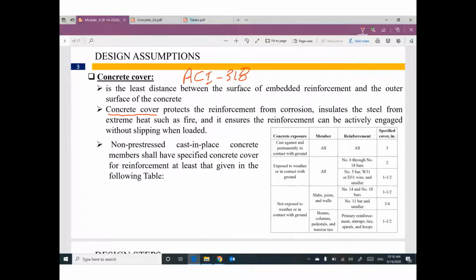So we need to protect steel reinforcement from any extreme condition, like corrosion, fire, salt attack, freezing, all of this stuff. Concrete resting directly on soil will be different from concrete in a building on second or third floor, and completely different from a bridge in contact with water. So we have different values of cover.